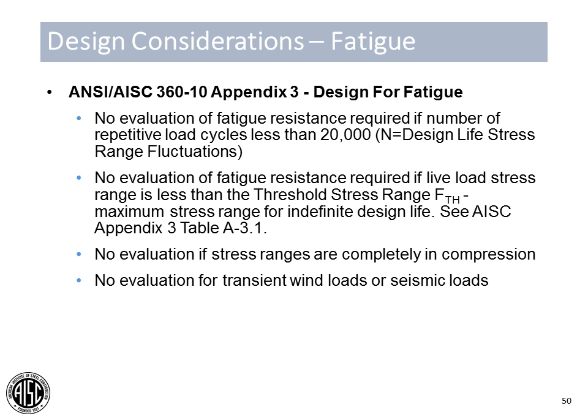Now, frequency, we said, is one of the critical items that we need to look at. Fatigue does not need to be considered for a system that is subject to less than 20,000 cycles in its lifespan. Also, the magnitude was the second item that we needed to consider. AISC specifies a threshold stress range, F sub TH, which is the maximum stress range for an indefinite design life.